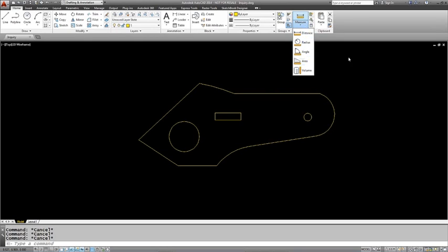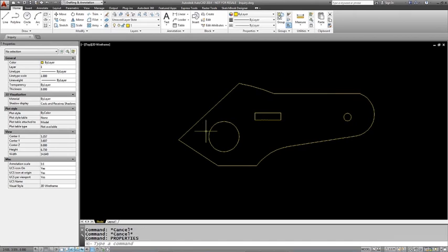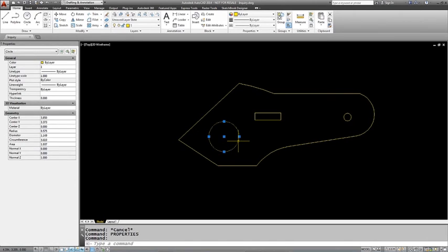But I'm going to show you a few shortcuts to save time when you're taking the exam. So for example, if I'm asked, what is the center point of the large circle? What's the ID point? Well, I'm just going to type in ID, find the center, and at the bottom of the screen, there's my X and Y value. That saves me time. I could go into, turn on my properties palette, and if somebody says, well, what's the diameter of that circle? I can go ahead and select the large circle, go into properties, Control C, Control V, in other words, Control C to copy out of properties and drop it into the input box in the exam.